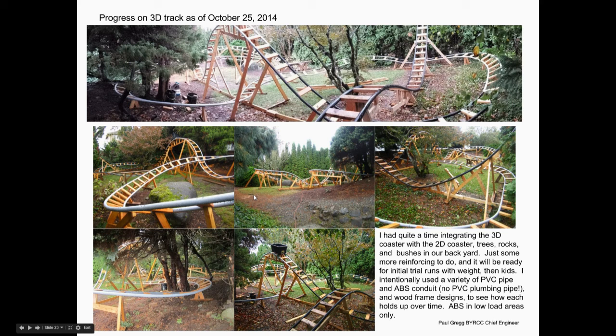And these are some pictures of intermediate stages of building the track. I start out with just the frames and then put longitudinal pieces in to stiffen it up, and then a brace up to every tie, and then some big diagonals in the end on these frames, which you'll see later, to really stiffen the whole thing up. If you've been following my channel, you know that I don't really like putting holes in cement and posts in my yard, and so that's why I build these frames. They're actually cheaper than 4x4 posts because they're made of 2x4s. I always put treated wood on the bottom brace, but 2x4 is pretty cheap, and so I think it comes out to about 20-30% cheaper than 4x4 posts, and it's a lot stiffer side to side, a lot better supported.